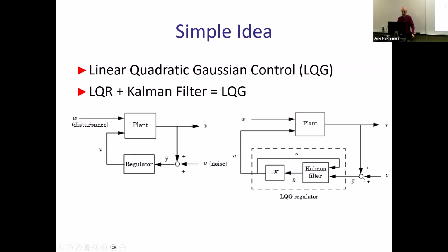So this is exactly what it says here. So you have Kalman filter, which gets input from here, and it's also producing that same input, by the way, that LQG thing. But you can also put it back into Kalman filter, because that's what you need. And also you put in error. You can include that maybe even in the box if you want to. So you have that error of the output, input. This is input for my Kalman filter. This produces estimated state as any observer. This estimated state is multiplied by K. And since I want negative return, which is negative feedback, I'm multiplying that by -1. And then I'm returning it back as U. So here I have already U for zero reference input. Okay, so I'm assuming a regulation problem, not tracking problem. So this is how it will look like in closed loop.